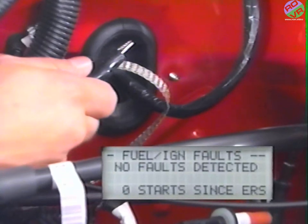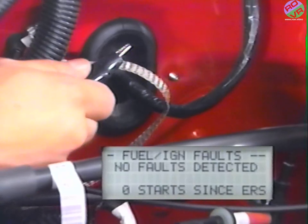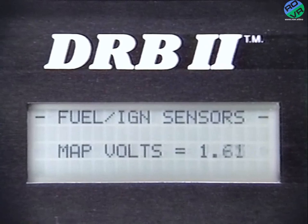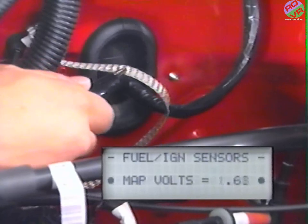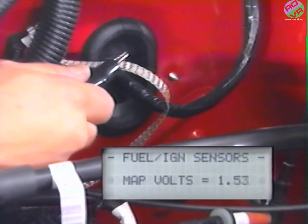When we ground the jumper wire, the DRBII shows that no fault messages are set. However, you can hear the engine reacting to the low MAP sensor voltage. When we read MAP sensor voltage while grounding the output wire, the reading goes to 0 volts. There's obviously a problem. But a fault will not be entered into the memory because the condition does not occur within the RPM range monitored by the arming conditions.